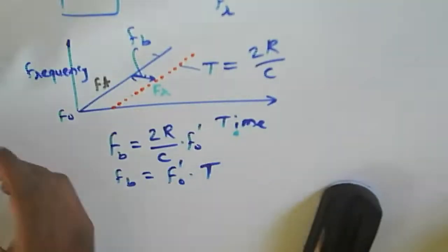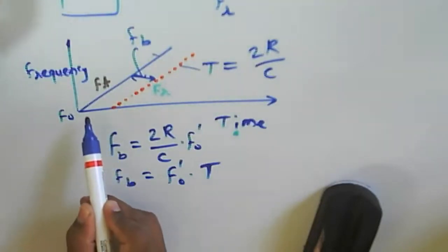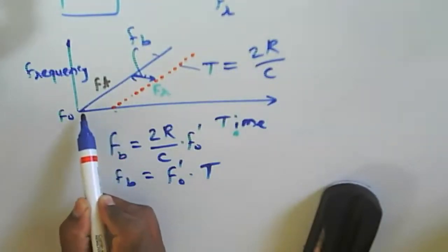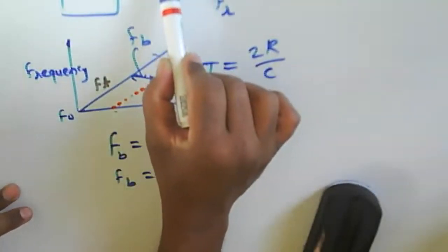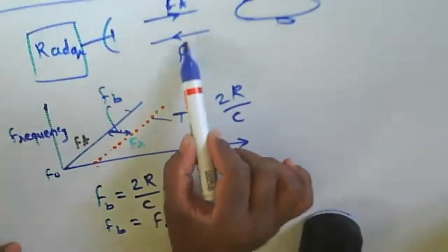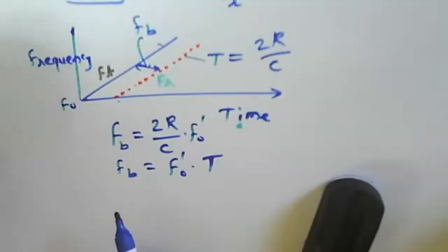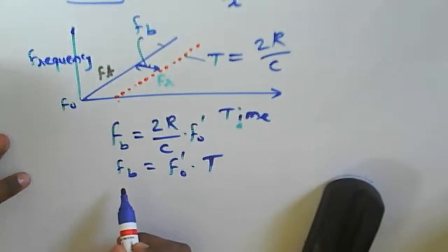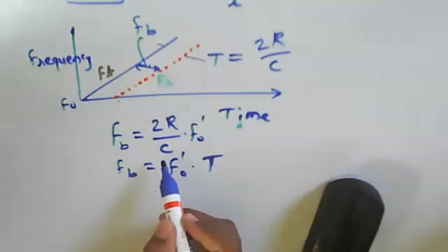So generally we consider that the beat frequency is about a time, a transit time, or we can say a two-way propagation delay, meaning the time for a transmitted signal to reach the receiving signal. This one is about a time here. This is called t here, and that will define the beat frequency, and f is nothing but the carrier frequency we have.